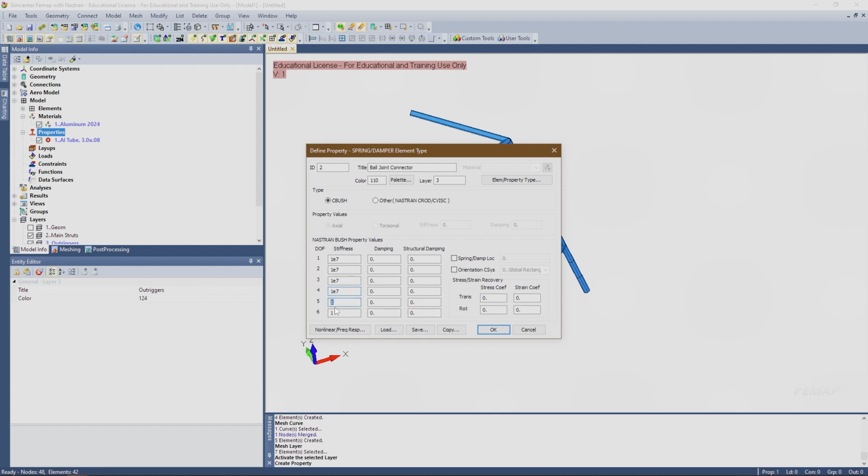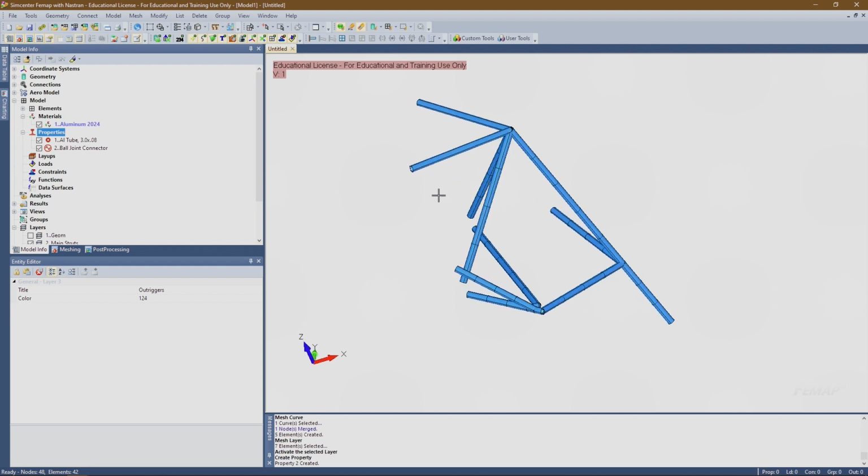We just want that swinging motion. A lot of people represent struts with this. It's not 100% physical, since struts do rotate around their own axis, but it generally doesn't matter. FEMAP can sometimes have issues with that because it sees it as an unconstrained direction. So anyways, I'm just going to rigidize the axis around its own rotation, and it really won't affect the analysis.